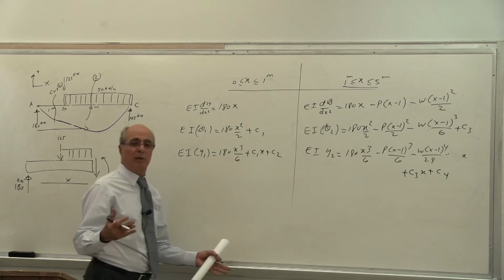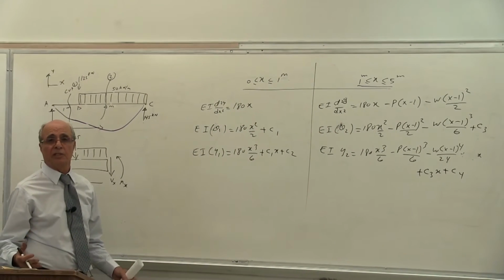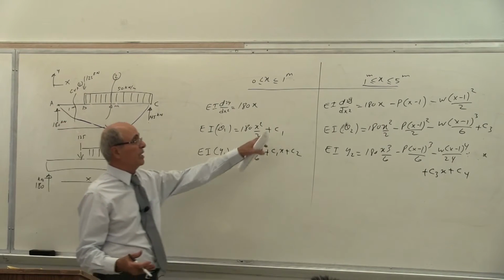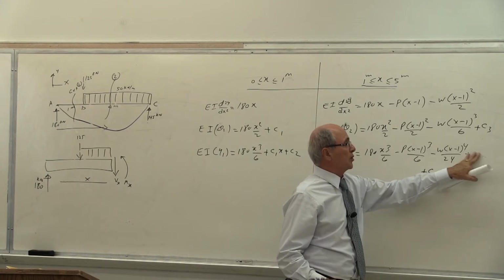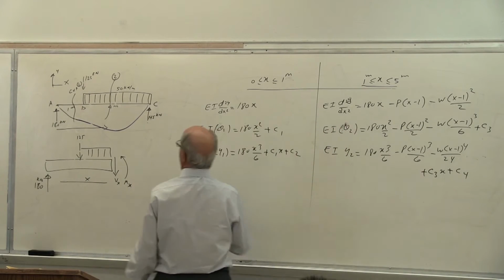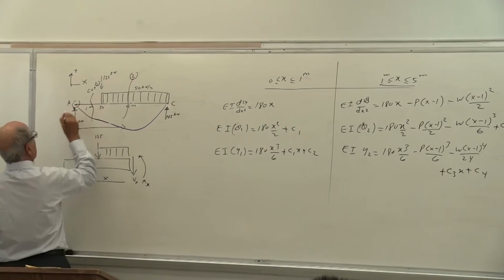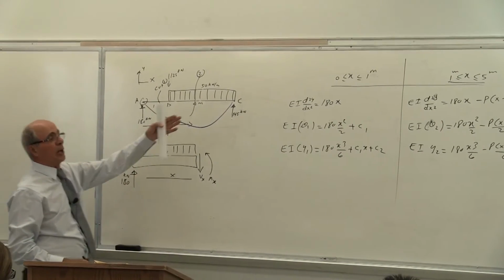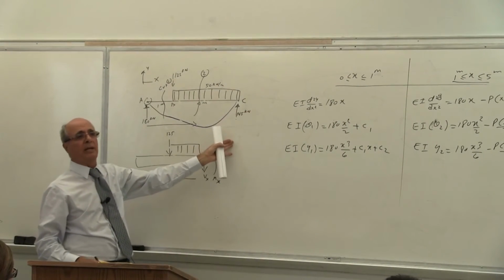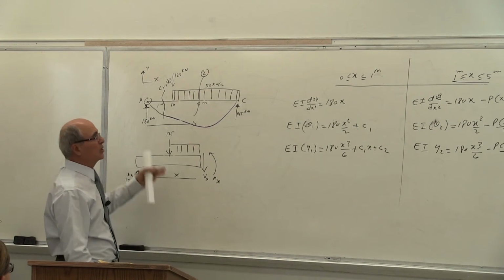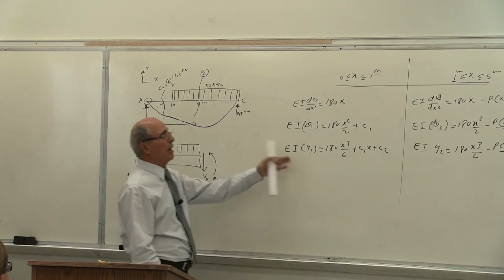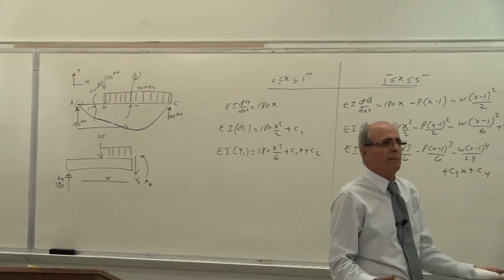I have 4 boundary conditions I have to resolve, for the constants of integration C1, C2, C3, and C4, with the system I showed you. Now, at X, look at this. This is the boundary condition, but it does not apply to the purple one. Some of you put it all over the place. Look at your notes, what you have written. Put X equal to 0, Y equal to 0. You apply it here, and again apply it here.